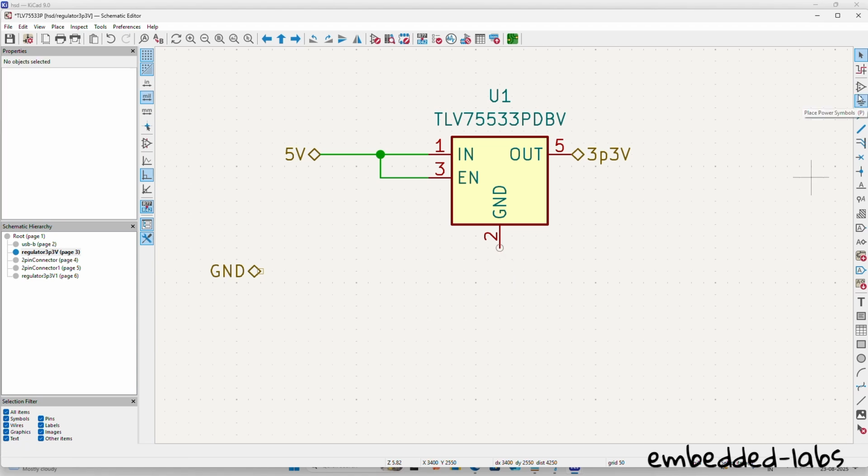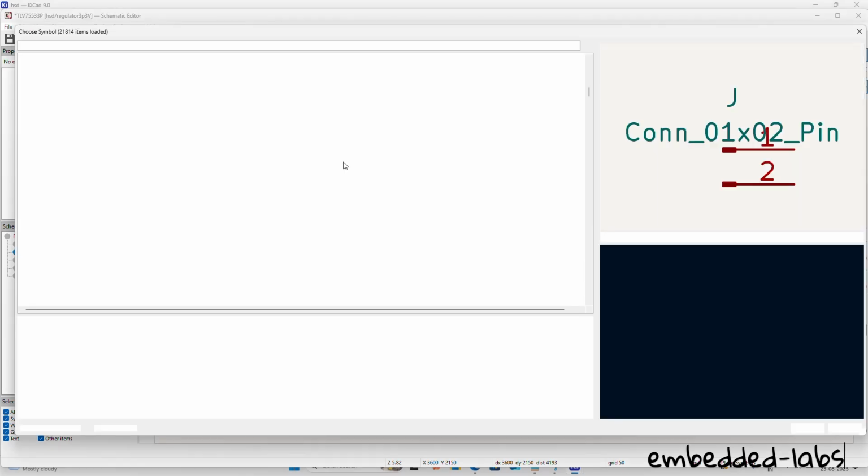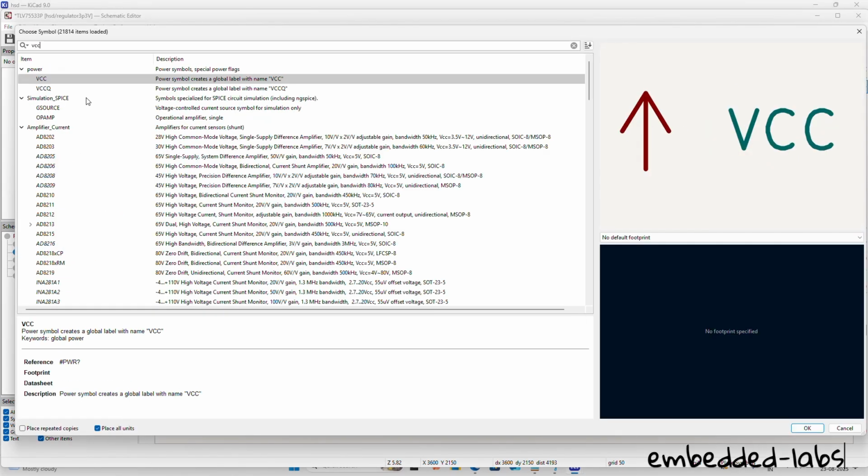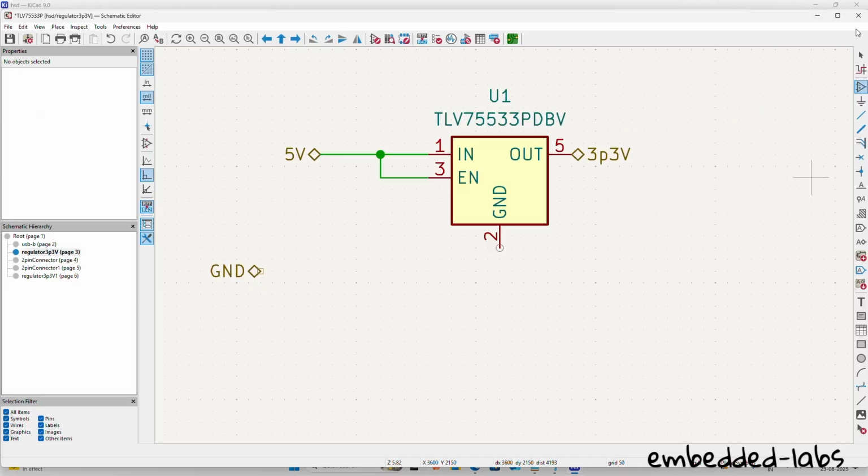You should also not use something like VCC. You should not use this particular symbol. These are global labels which are even accessible outside the blocks. So let us say you don't want to have a direct connection here because the circuit is a bit complex. You place a net label here. That is what you typically do.